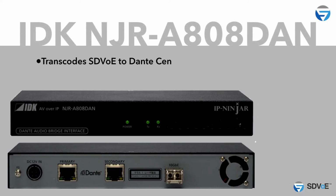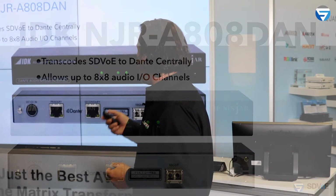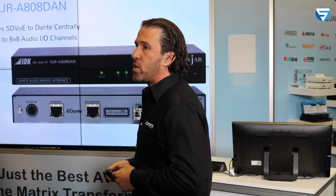So IDK, they did something interesting here that I give them credit for, which is they're doing Dante in a centralized format. So whereas we're doing a decentralized approach, they're doing a centralized approach where it will allow the breakaway switching capabilities of the SDVoE to route it into their box, assign it to a Dante channel, and then obviously redistribute it back out through a Dante. Another methodology of doing it, but it's the first of its kind where it's an audio-specific product into the SDVoE environment, and this is how you can also bring Dante and SDVoE together with this bridge.